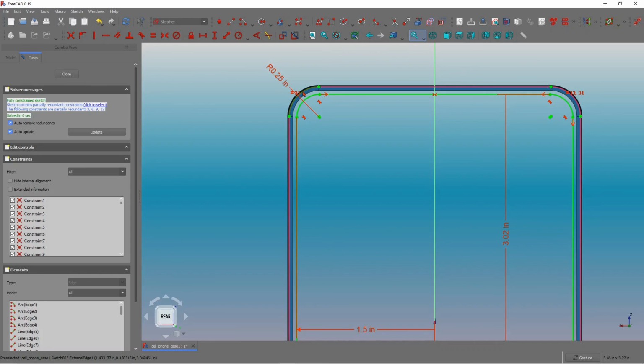You can delete it because they are not connected to the previous sketch, and by deleting this you're not impacting the parent of the sketch. So you can just go and delete it. I'm going to press delete. Unfortunately it has two things. There's an edge attached to it, so you have to delete both of them and keep deleting that.